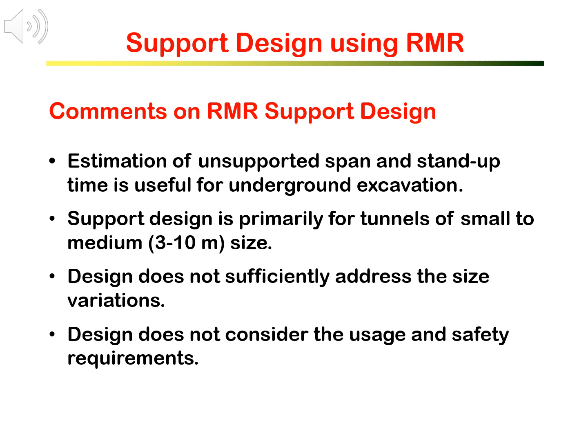Using RMR to estimate stand-up time and the maximum unsupported span is particularly useful in underground excavation, particularly in relatively low-quality rock mass. It helps to determine the advancement of each round of excavation and the timing for support installation.